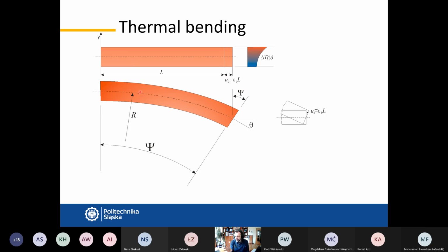So small deformations, where we are within the Hooke's law region, so stresses are not bigger, we do not enter into the plastic area or elastoplastic deformation. We have the beam relatively narrow, which means that the lateral contraction or lateral expansion, which results from the Poisson's effect, as you may recall, is negligible.